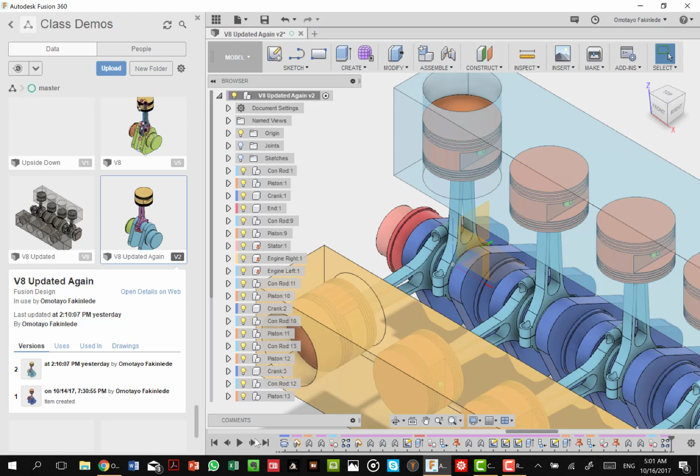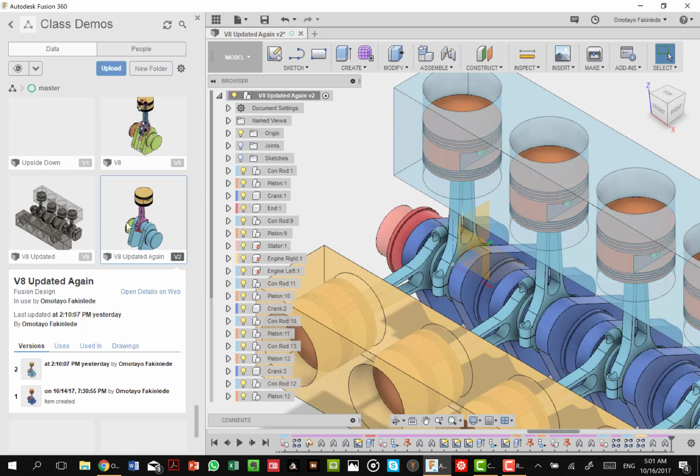Those joints that are not contained within components, we will have to manually apply after the pattern creation. Apart from pattern creation, all these steps are the application of as-built joints, just exactly in the same way as we have done in the previous example.